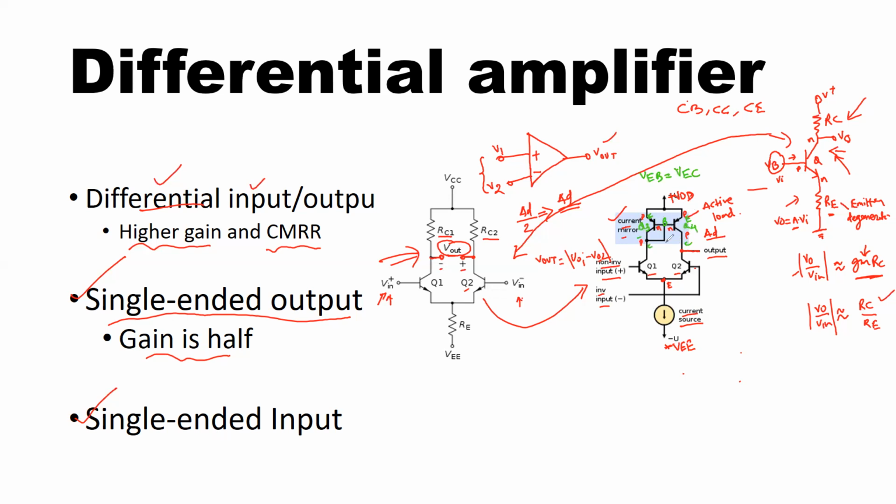And this is possible because you have shorted the collector and the base pin of the Q3 transistor. That makes the transistor always operate in the linear region. That is the region to the right of this line. This is your linear region where the current is constant. Okay, because of this arrangement, you don't let the transistor saturate. This is your saturation region. This is your linear or active region. Okay, and with that, it provides you a constant collector current that will flow through the transistor Q1.